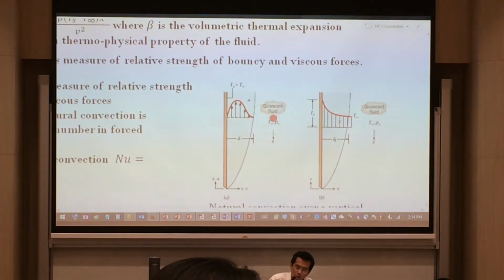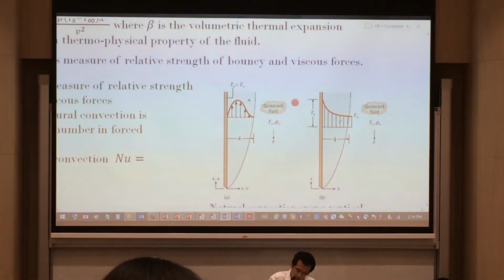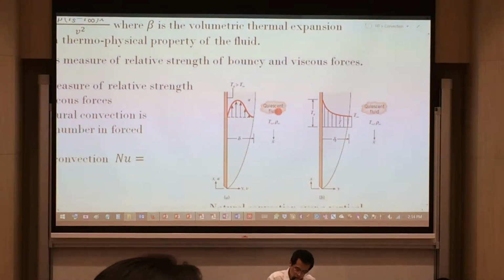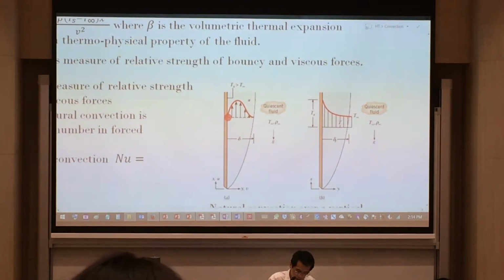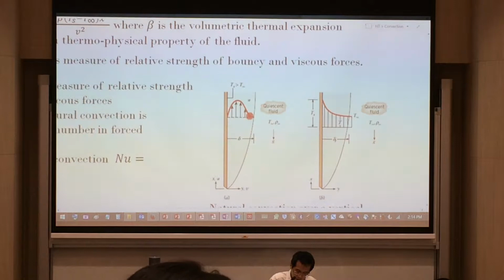This fluid would have zero velocity as well because, again, this is a picture of natural convection. It's not forced convection. So out there in the quiescent fluid, there's no flow. Unlike what you have seen before for forced convection, where in the ambient region there is flow, in this case there's no flow. So you have this part here that has a velocity of zero, and that part there that has a velocity of zero. And the profile of the velocity will look something like this.